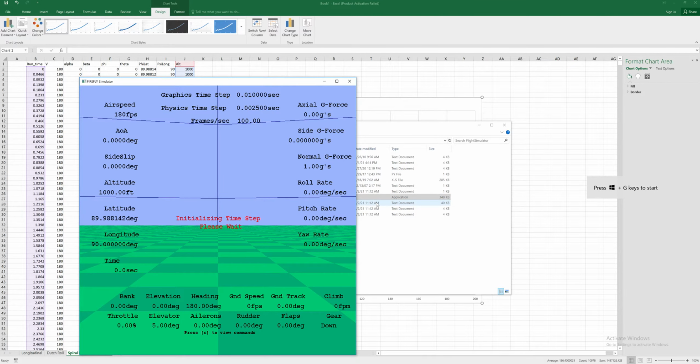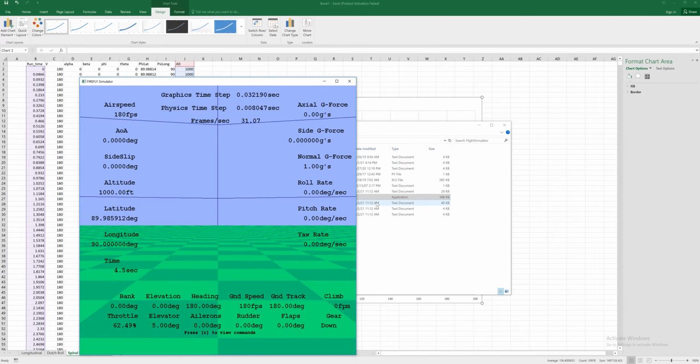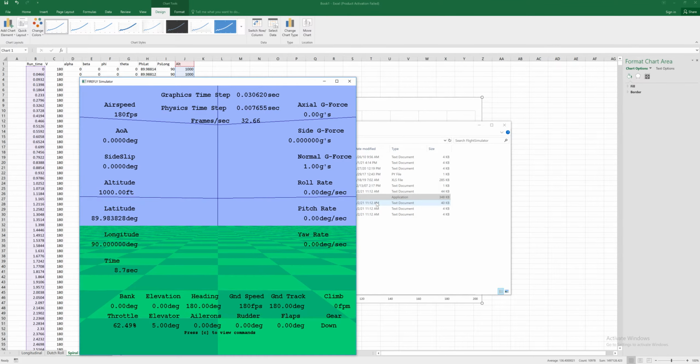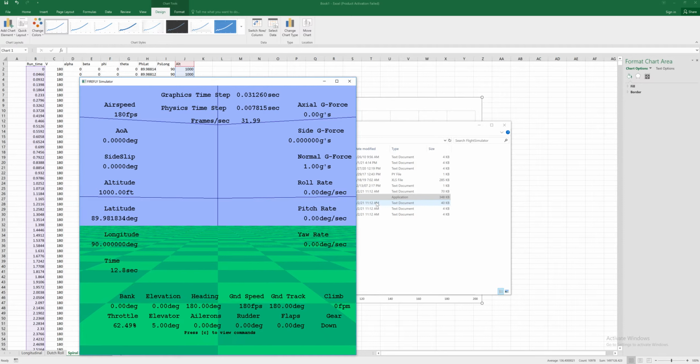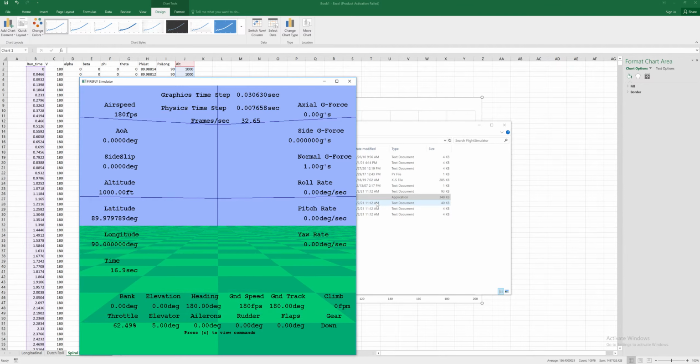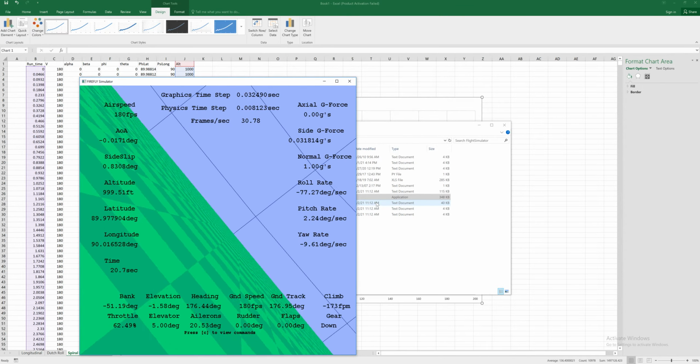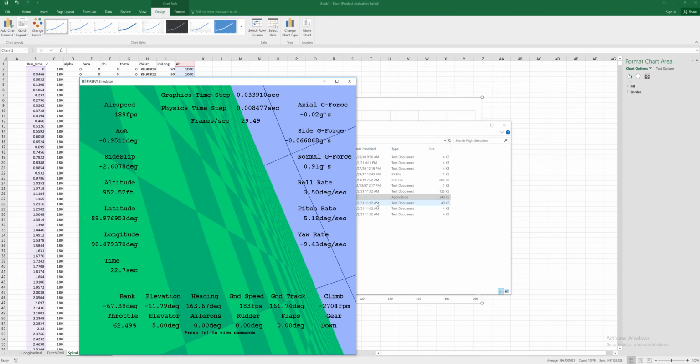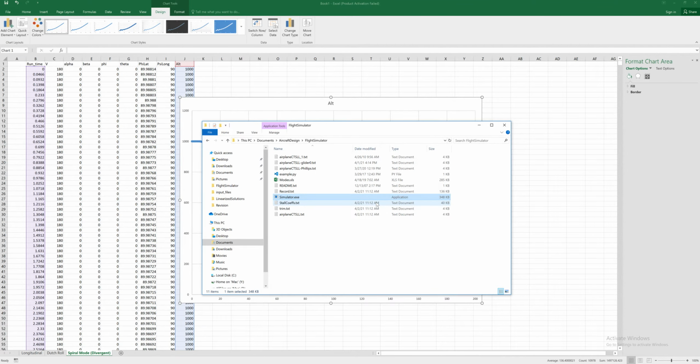Okay, so to excite the roll mode, what I'm going to do is put it in step aileron change, okay? And I'm actually going to hold it for just a second. So I'm going to hold the aileron to the right for just a second and then return it, or actually it's probably going to go to the left here and then return it back to neutral. But I'm just going to hold it out there for a second, then bring it back. Ready? So here we go. Okay, so that's actually long enough to pull out the roll mode.